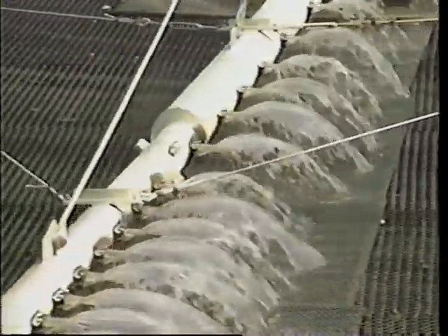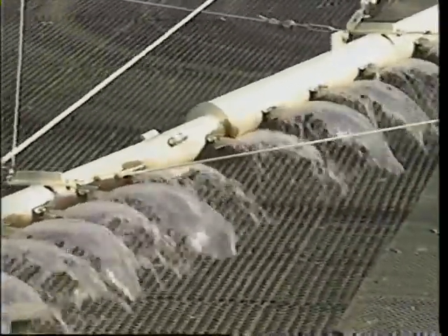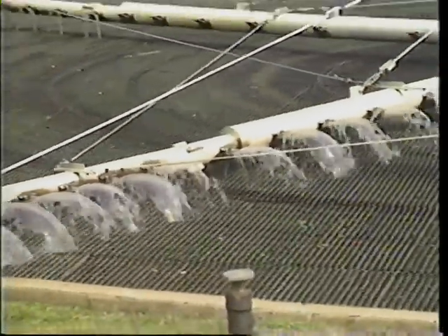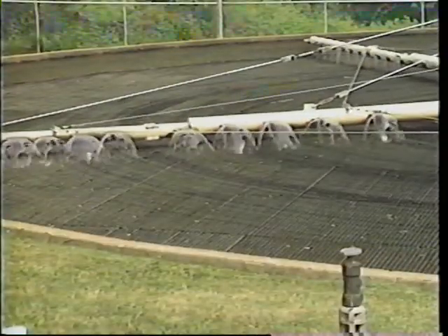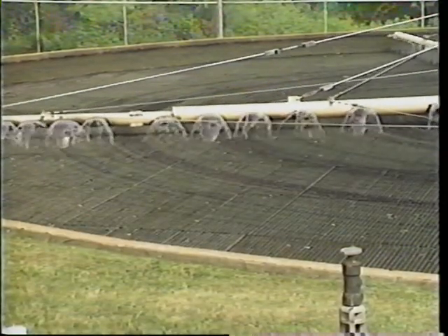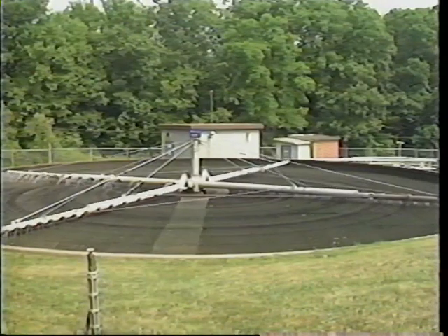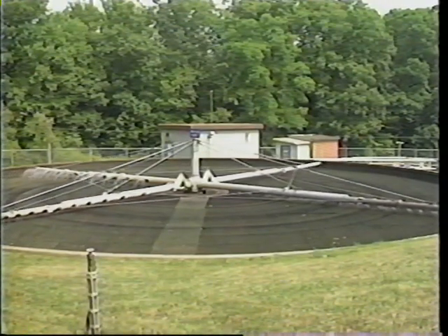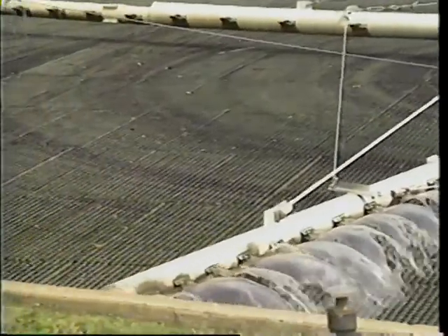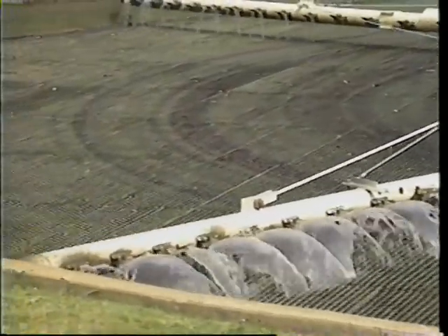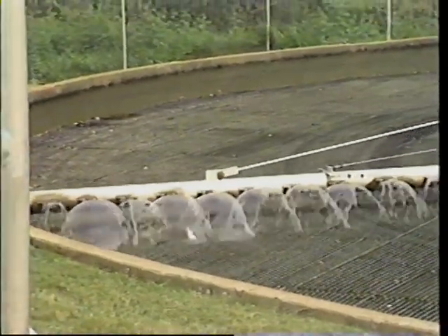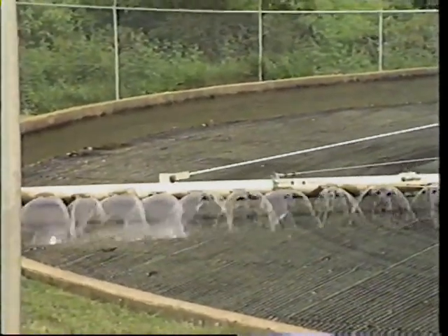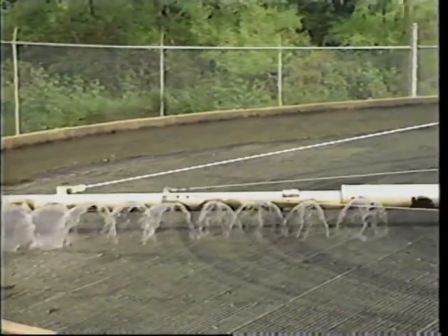Effluent from the primary clarifier is spread over the media by a rotating distributor or fixed nozzles, and the wastewater trickles over and around the many faces of the media and is collected in a channel at the bottom of the unit. The trickling filter does not remove any solids with any filtering action. Instead, the bed of media offers an environment conducive to organisms which attach themselves to the media and feed on organic material in the trickling water.